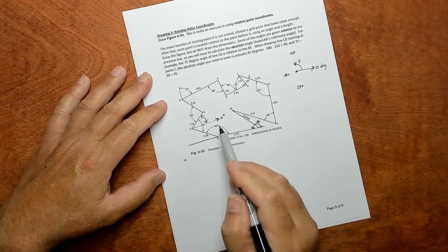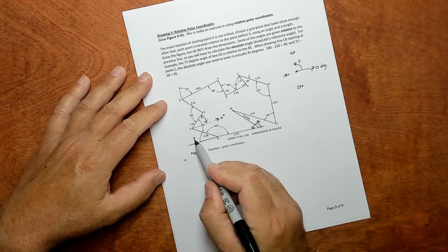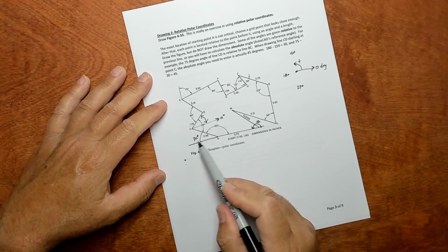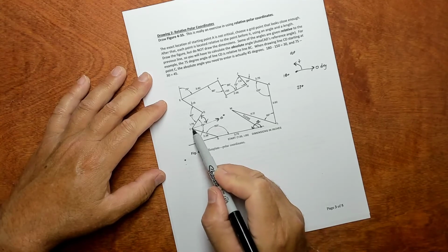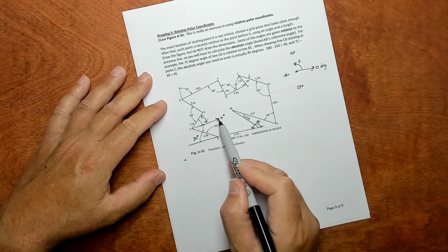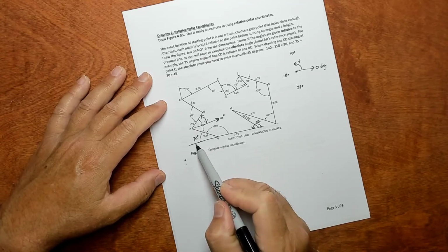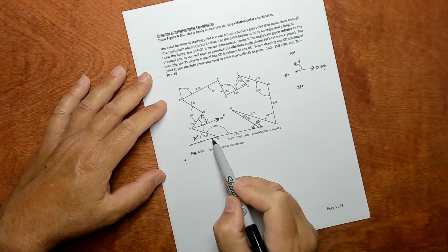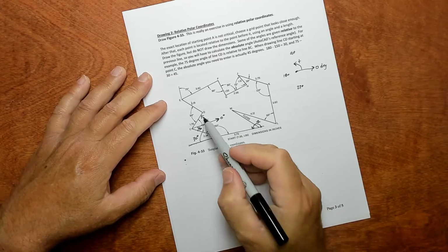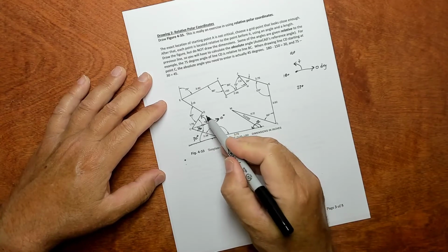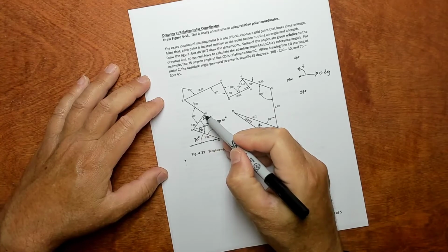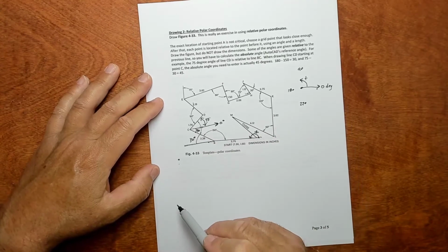If this is 150 up top, this in here must be 30 degrees, right? Because 150 plus 30 makes 180. Okay, if you then consider this line, it's just a horizontal line straight out at 0 degrees. That would be parallel to this line down here. So that means this angle in here would also be 30. Okay, then they've given us 75, so the remainder must be 45. So what you have to enter in the CAD system is 1.75, comma 45.